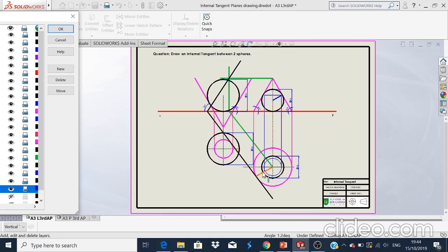Also what we've done here is we've drawn our normal to our horizontal trace. That's just drawn at 90 degrees, which can be done with your sliding set squares. So we have our normal in our plan view, and we have our normal here in the elevation. The two of them are just drawn with your sliding set squares, set them up parallel with this line, and then 90 degrees into this. So what this gives us, where this is brought down, and where that circle arc crosses this line, that is our point. I'm going to show this now in the next step.